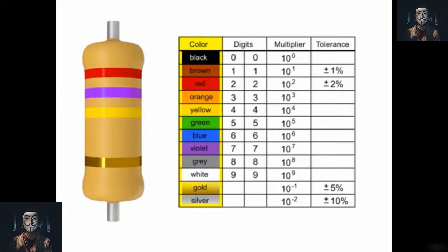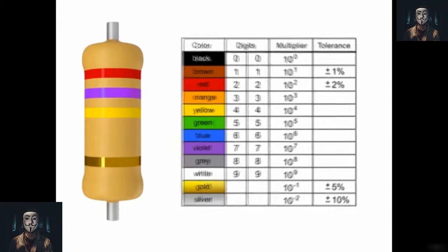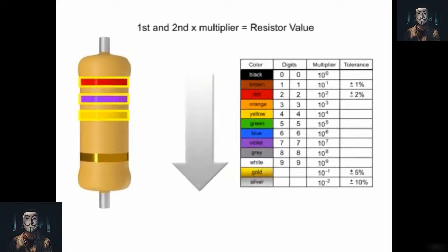If the current flows through the low resistance, higher current flows to the motor and its speed increases. If the switch is placed in the low speed position, additional resistance is added to the circuit. Less current flows to the motor, which causes it to operate at a reduced speed. A stepped resistor is also used to convert digital to analog signals in a computer circuit. This is accomplished by converting the on-off digital signal into a continuously variable analog signal.